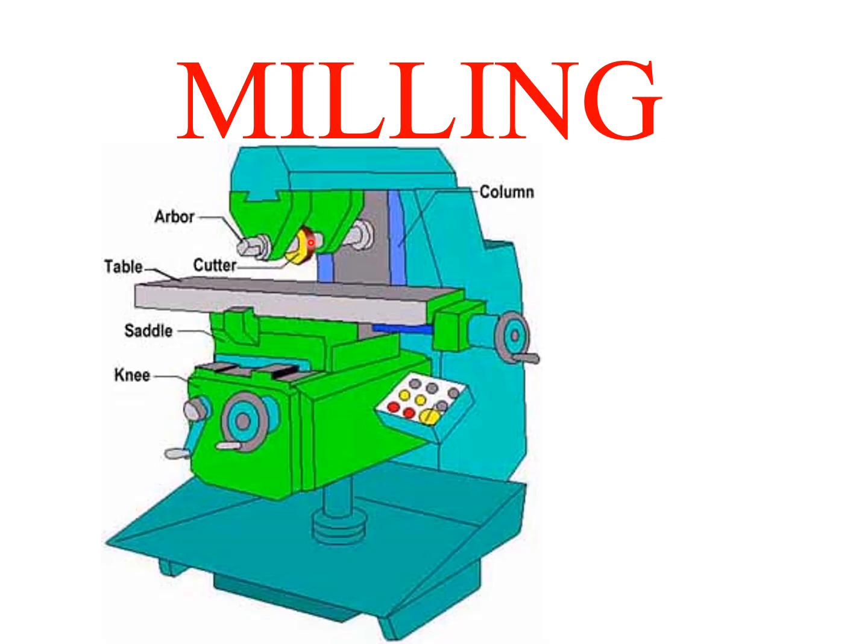Therefore, they should be selected reasonably according to the machining quality, machining efficiency, and machining procedure. Generally, machining efficiency is the first goal in roughing machining, so a larger cutting depth and cutting width should be selected. Quality of workpiece surface is the main goal in finishing machining, so a smaller cutting depth and cutting width should be selected.